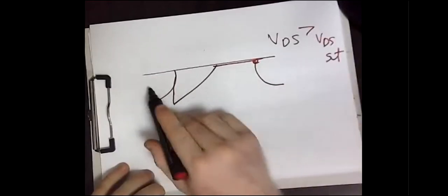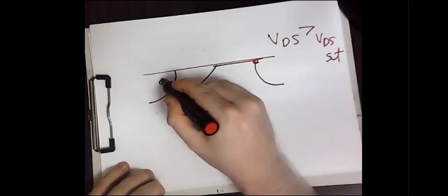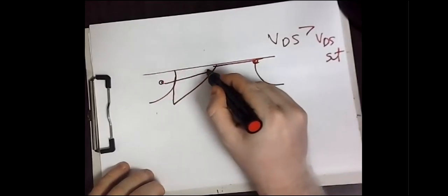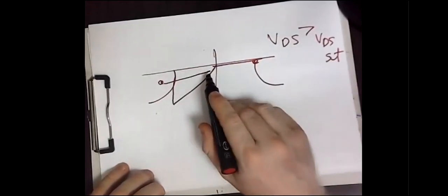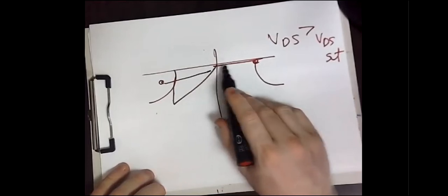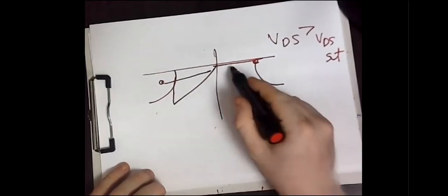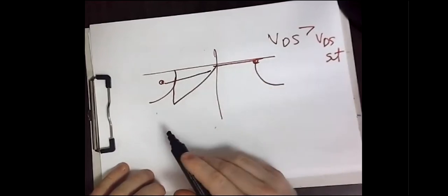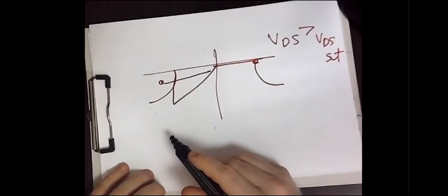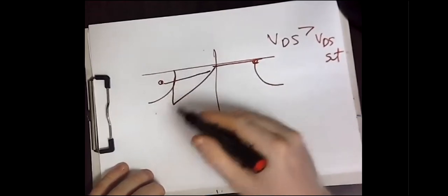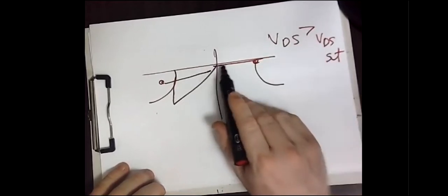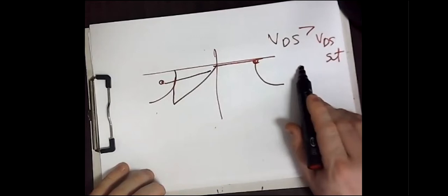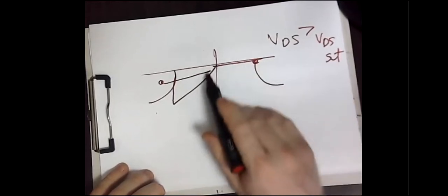However, as you can see here, the electrons will start to move on the bridge, but at a certain point, the electron will find that the bridge is no longer continuing, and this region is not an n-type region. And by the way, it's also not a p-type. Why? It's not an n-type because there is a high attraction force here. Whenever you have an electron here, this electron is directly attracted to the drain. So no electrons stay here.